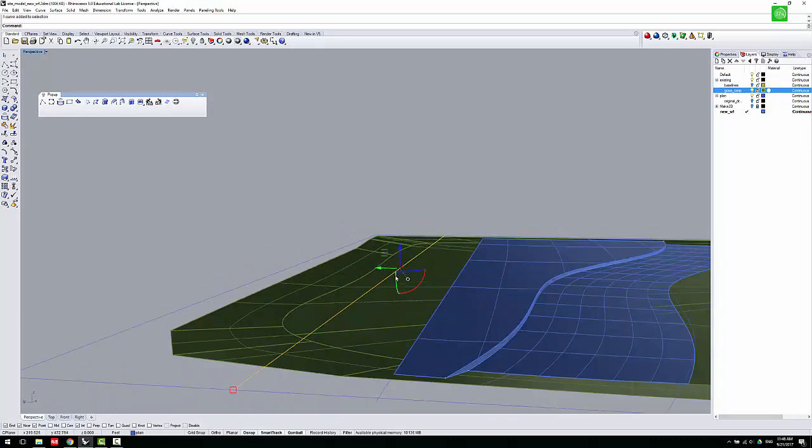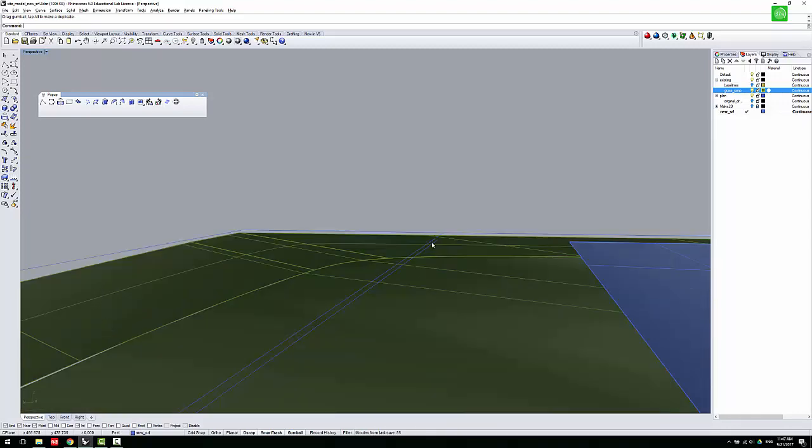Actually, this time we want to copy. If you want to go down, you just hit Alt. See here, you can move down and move up, and you can release. So it's always going to copy. And then we hit negative 0.5, hit Enter and release. So this line is going to be the same elevation as here.